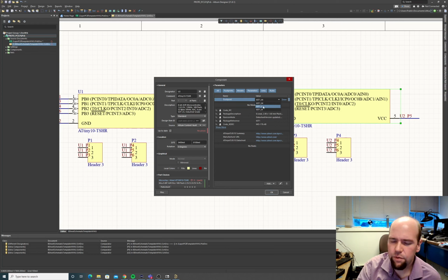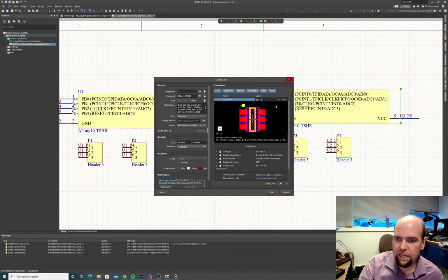Yeah, so there are several footprints here. Usually these are low density, medium density, whatever. A lot of times you'll see these labeled 1, 2, 3, or sometimes large, small, medium, or high density, low density, medium density. I don't know what the N and the L mean. My guess is this L is going to be lower density, so my guess is the pads are going to be bigger. We can look at these.